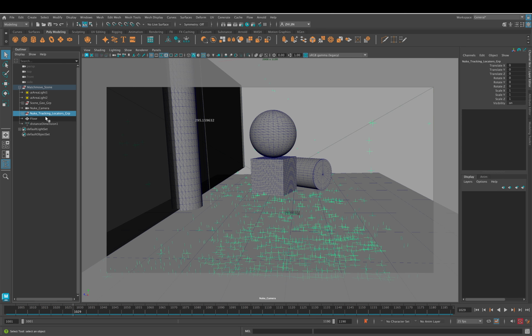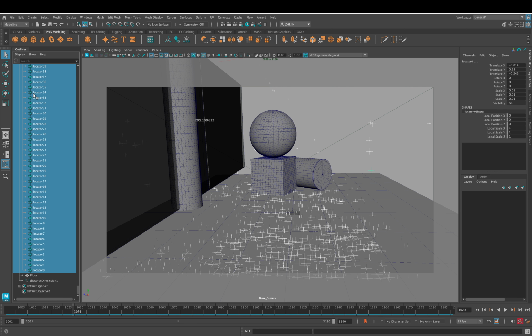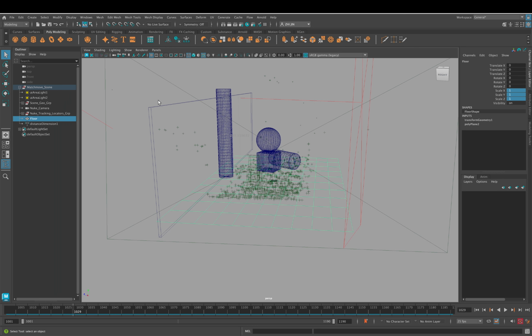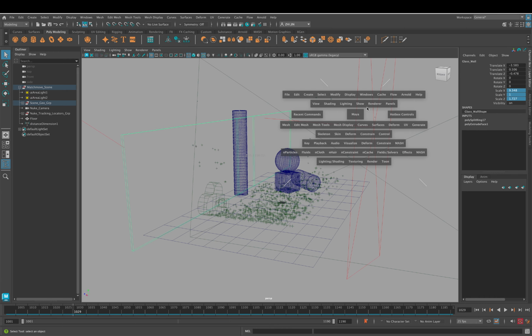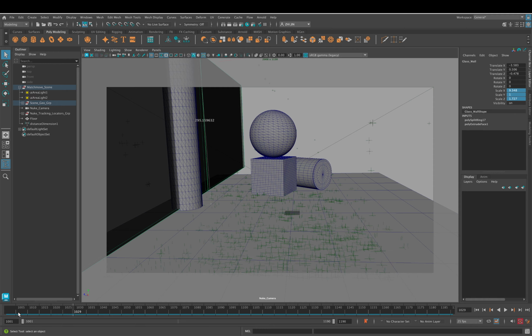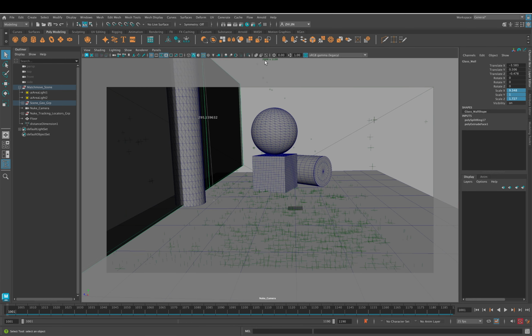Then after that, tracking locators, they are all the tracking features actually. By default, these locators are looking huge. So we select all the locators, change the XYZ from default 1 to 0.01, so they look reasonable to us. And also, based on the tracking features, this is the glass door we created and later will be used for rendering purposes. The camera size is 2008 by 1130.